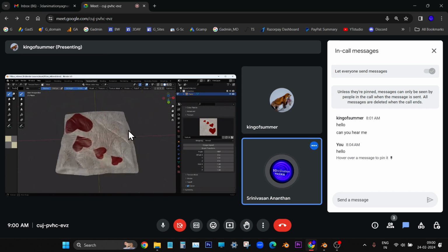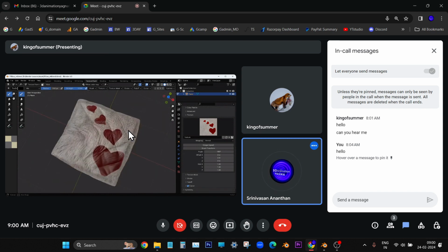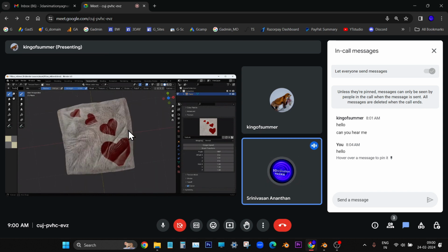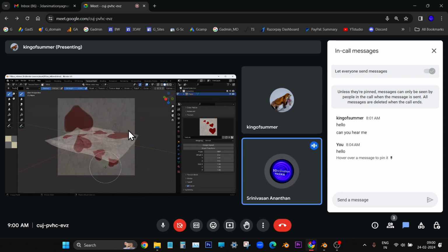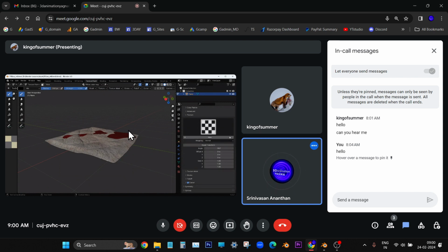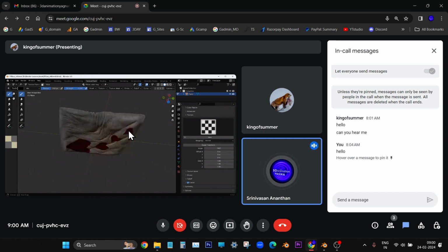That is bottom side. No, middle click only. Yeah. So both the sides are done. Okay, fine. Now we don't need this stencil image anymore, so you can close it. Where to close it is right side, go to properties panel. You are seeing an into multiplication kind of symbol, close icon. Yeah, that's one. Yes, close it. Yeah, that's all. So you'll be free from this stencil image.